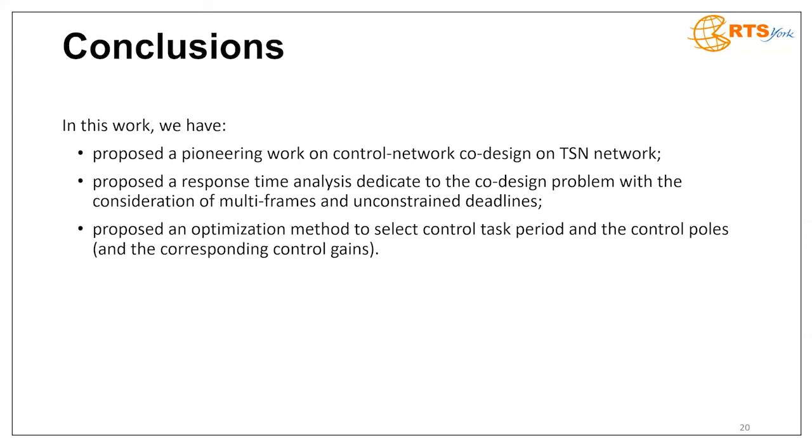As conclusions, in this work, we have proposed a preliminary work on control and network scheduling co-design on TSN networks. We proposed a response time analysis for the proposed schedule with the consideration of multi-frames and unconstrained deadlines. We also proposed an optimization method to select the control task period and the control pause.